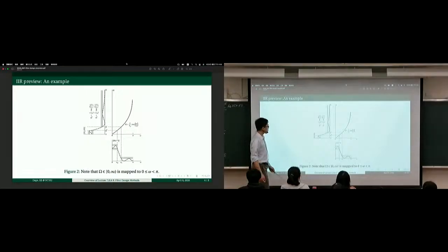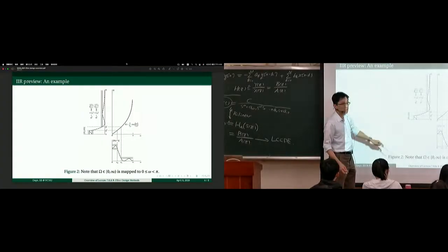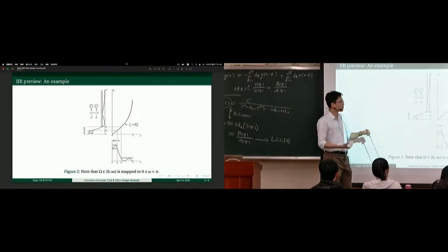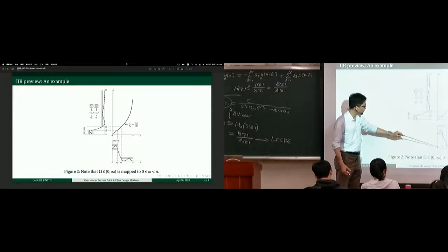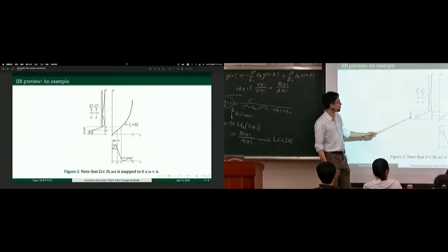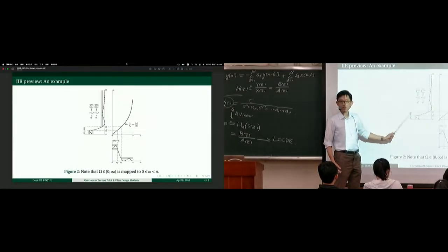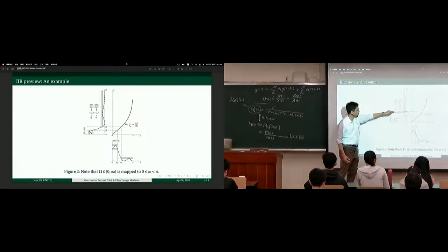But then, the bilinear transformation gives you this. If you take a look, here the frequency axis is big omega, whereas right here, that's small omega. So actually, after the bilinear transformation, the frequency axis is compressed to within this interval, 0 to pi. And that's very nice. By doing so, we convert an analog low-pass filter to a digital low-pass filter through this frequency compression.